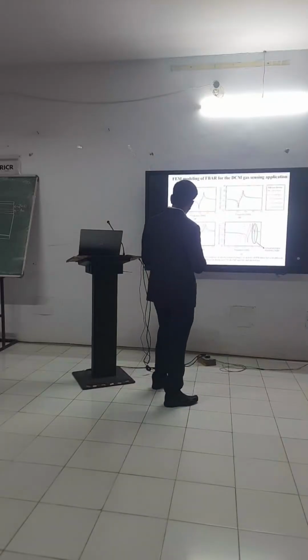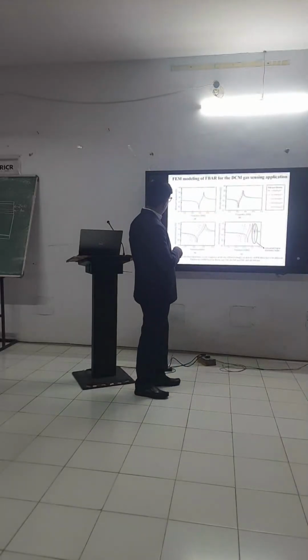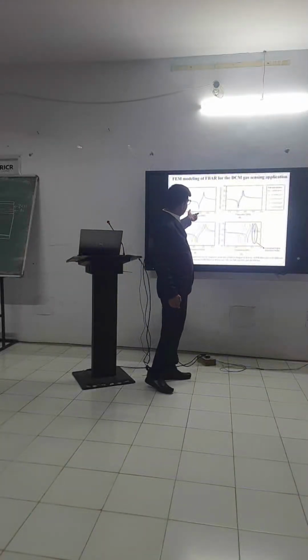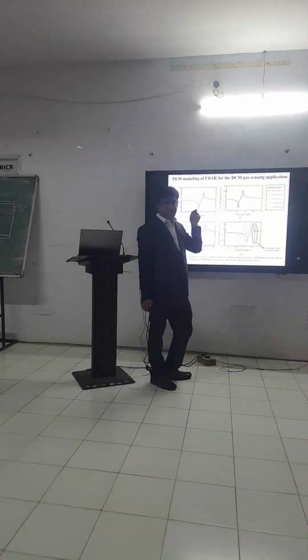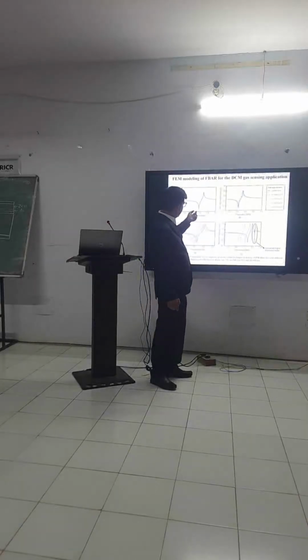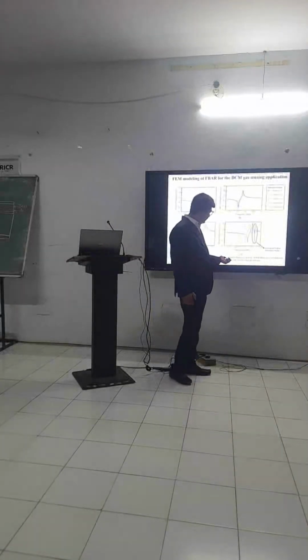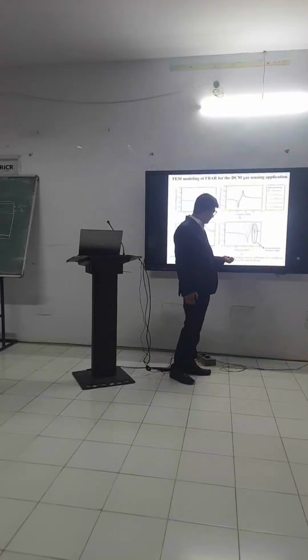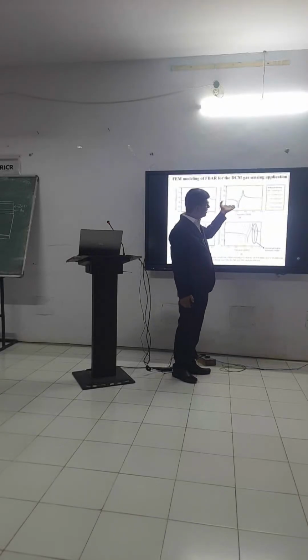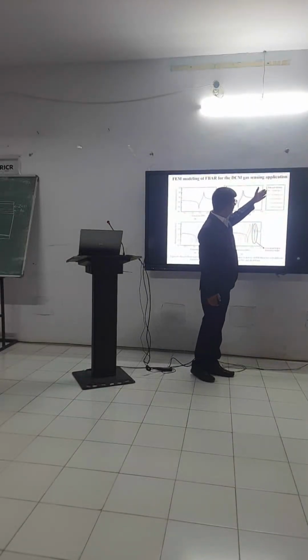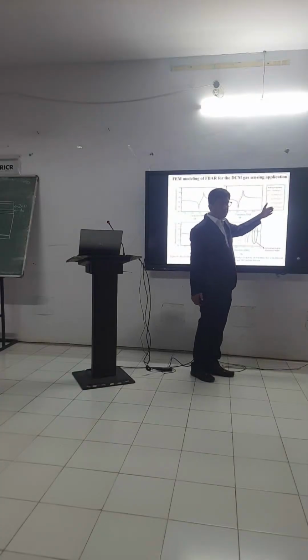So see here, what thickness did I start with? I started with 170 nanometer. In this case, I kept my sensing layer at 170 nanometer thickness. What happened? There is no change in frequency. Clear? Then I doubled the thickness of my sensing layer from 170 to 340. Now there is a little bit of change in the frequency once I have increased the concentration.